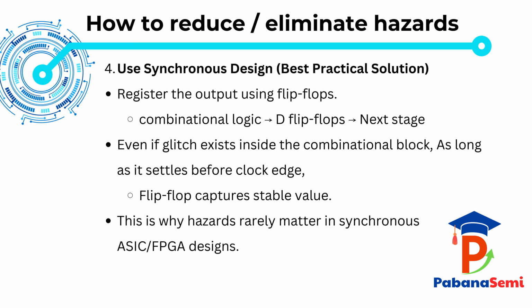So the takeaway is simple. If you design synchronously and meet setup and hold timing, glitches become an internal timing artifact, not a system-level bug.